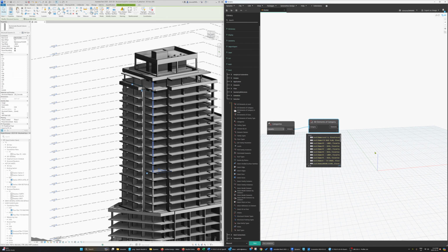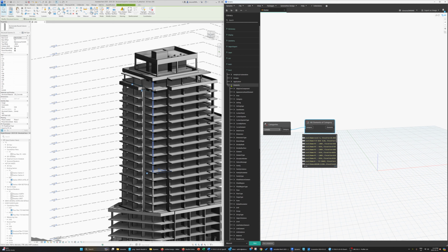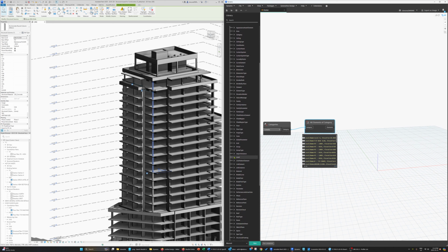So once we've selected this, I want to be able to extract the elevations of these. So we have an elevation marker here. We can tell 55,000, 57,000, 58,000. So we have a lot of valuable information. In order for us to extract these elevations, we're going to go into level elements, we're going to go into levels, and I'm going to extract the elevation, so the elevation of the level above the ground level.